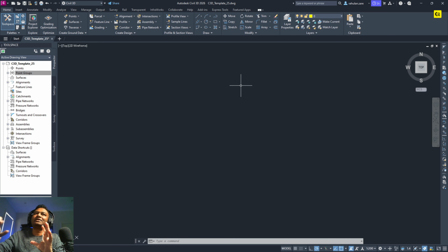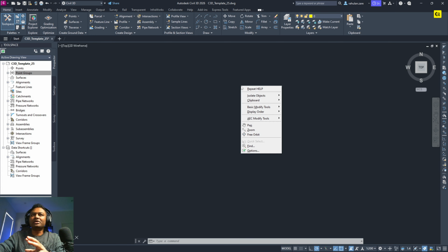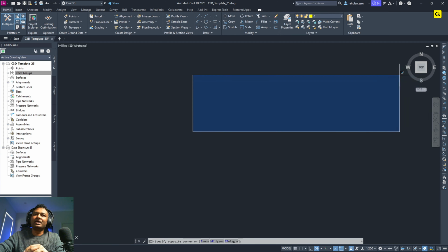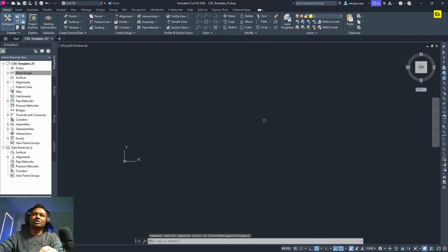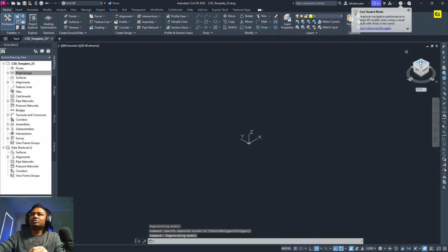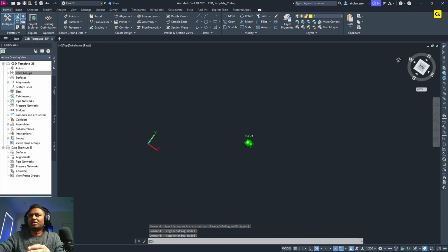If you want to rotate and see it, there is a separate view, which we call the Object Viewer. You basically select the object on the screen, right click, and you will see another button come up called Object Viewer, so you don't necessarily have to rotate on the screen. And if you want to reset the view and rotate, you can use the View Cube to rotate the object and the screen, and then view it at a special angle that you want.